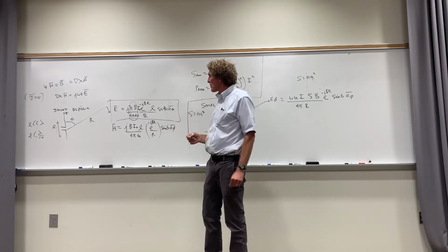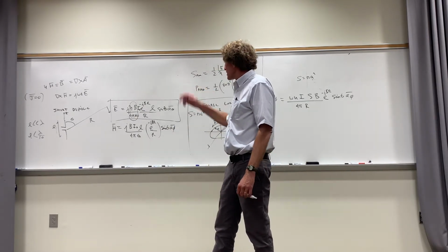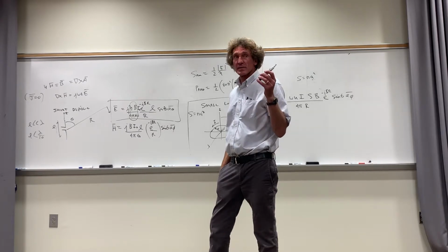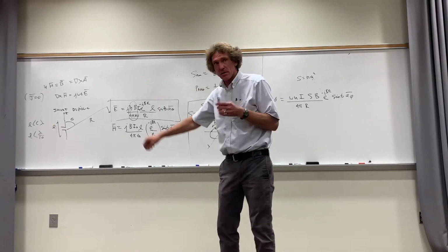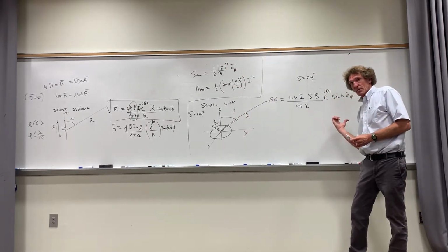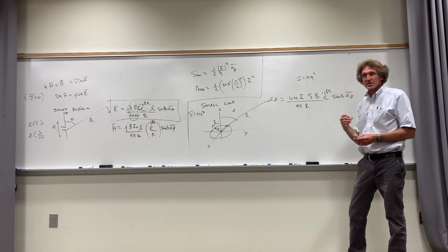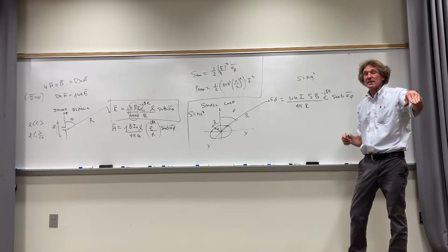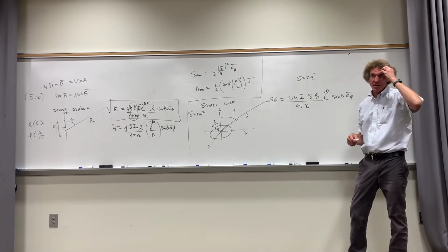Where is it a maximum holding r constant? Say we have r at 100 meters. Where is the electric field in terms of an angle of maximum? 90 degrees. That's called broadside radiation if it's a dipole. Here, where's the electric field maximum? Right in the xy plane, right? Or at theta equal 90 degrees also. They have the same radiation characteristics in terms of their intensity. The E field is polarized in the opposite direction, all right?